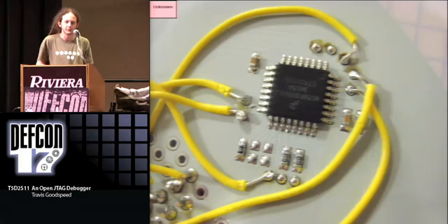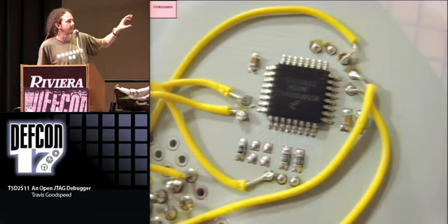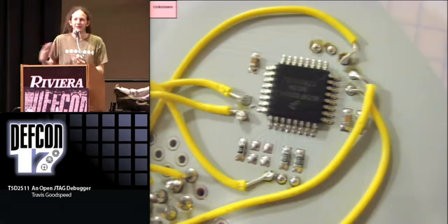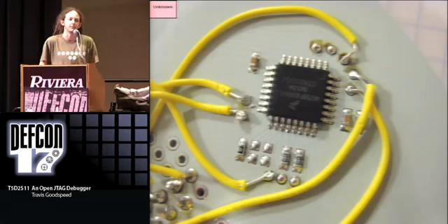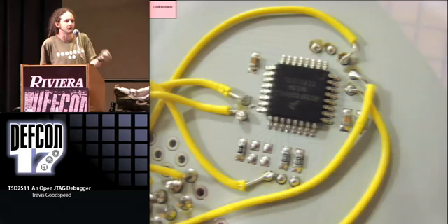And if you put a fresh chip onto your board, after the lecture, we'll be blowing mine up in the name of science. So I'll need to swap it out with another chip. And when I put that fresh chip onto my board, it won't have a bootloader. And it won't have the software that it currently has. It won't be blinking, it won't be running anything. So the only way to flash new software onto it is by JTAG.